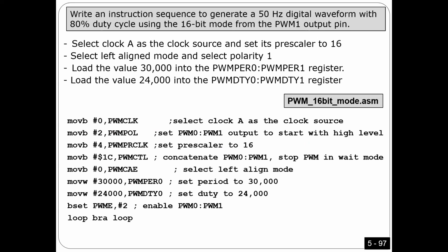Anyway, this part is not in the final exam. At least you should understand what is pulse width modulation. Programming-wise, very trivial. You don't need to do anything programming. Just write to register. That's it, right? And then after you write to register, you have 1 bit to turn on and off. And then you have two registers, one for duty cycle if you want to change the duty cycle, and another one for the period, if you want to change the period. Is that okay?